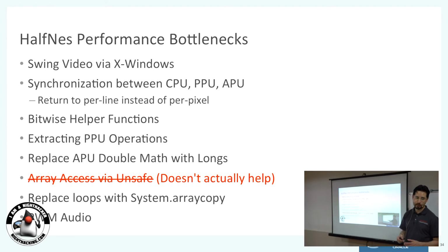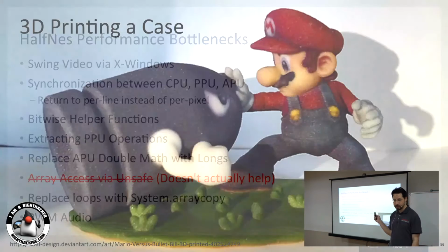It's slightly hidden under the logo, but on the Raspberry Pi, audio was another big bottleneck, because whenever you flush the audio buffer, the audio is written via pulse width modulation. It's quite slow to do buffer flushes. So rather than flushing once per frame, which is 60 frames per second, I flushed the audio buffer once every 3 or 4 frames. That causes a slight delay in the audio. So it's not perfect for sound effects or certain things, because you get a slight lag. But I think if you were playing, you probably didn't notice too much difference, right? Losing 2/60ths of a second isn't too bad for audio sound effects. So this is some of the performance things which I fixed.